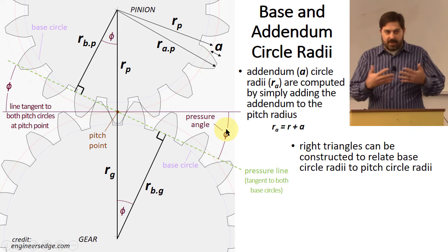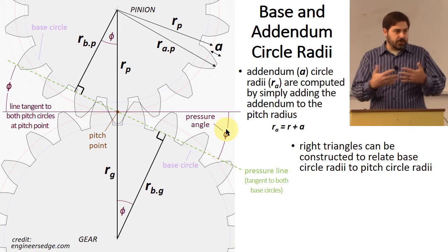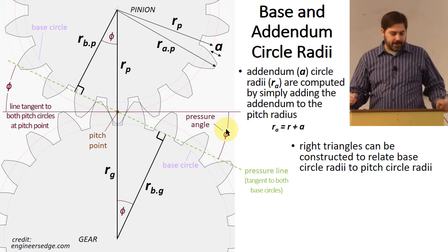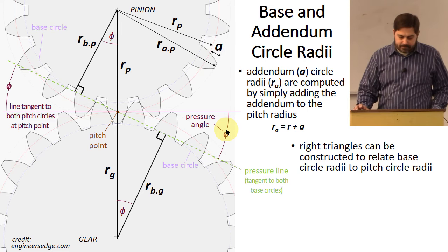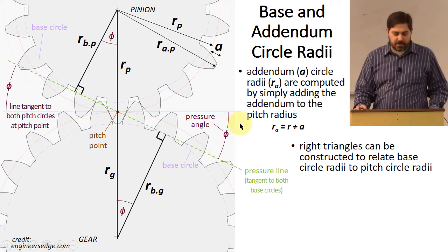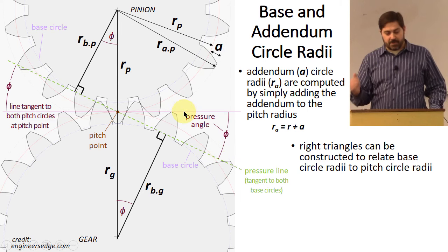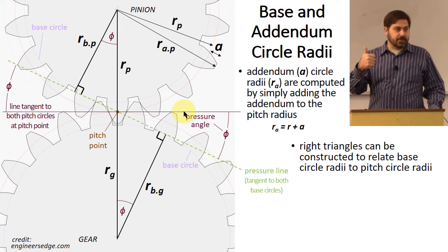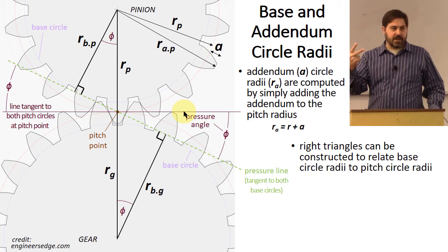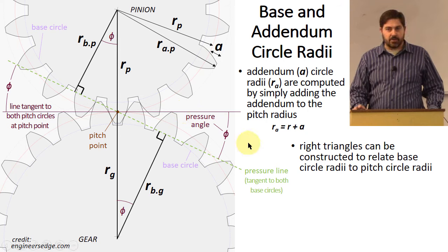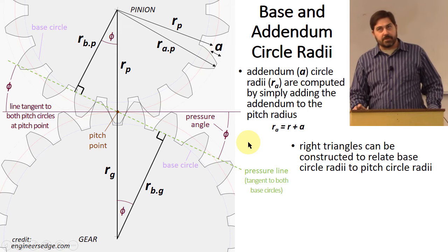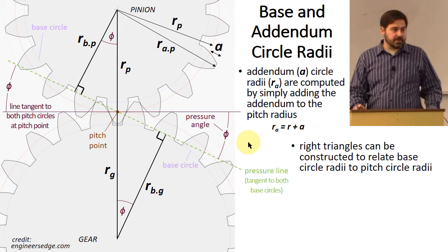Two gears need to have the same pressure angle in order for them to actually transmit torque properly. And by the way, there's not actually that many choices practically out there in the world for pressure angle. Generally, you will find ones that are either 14.5 degrees, 20 degrees, or 25 degrees. Those are the three big standards for what a pressure angle might be on practical gears out there in the world. There are some other ones, I believe I've heard of ones that are 30 degrees.